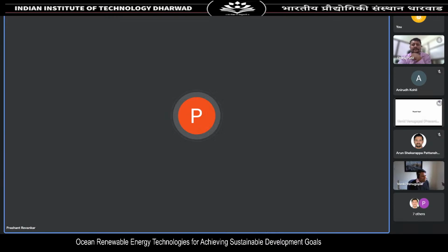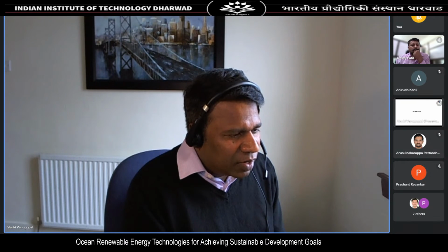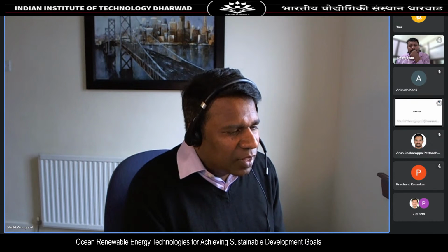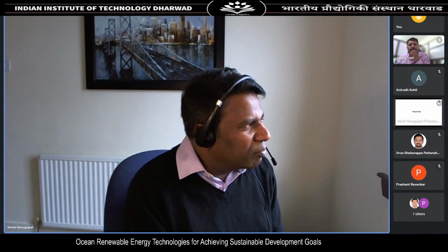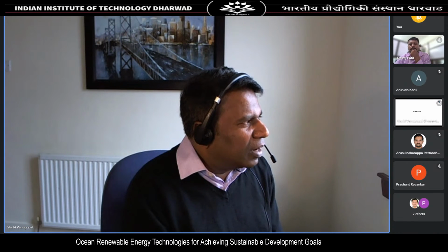There's another question which asks what grid size you are using for the numerical approach that you adopt for the study. That's a very good question. If you are doing a tidal numerical model, then we have to satisfy the CFL number, which would usually be 0.5 for a tidal model.